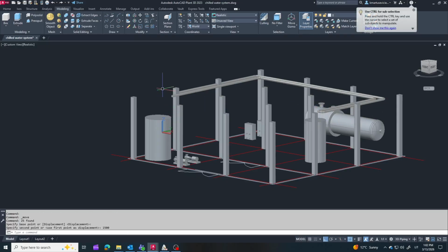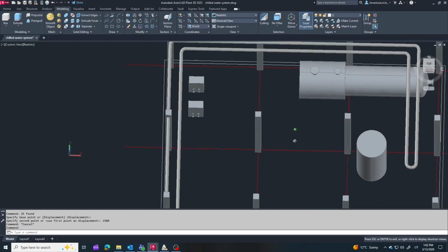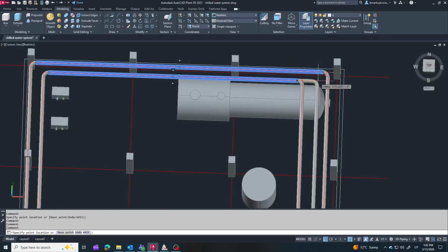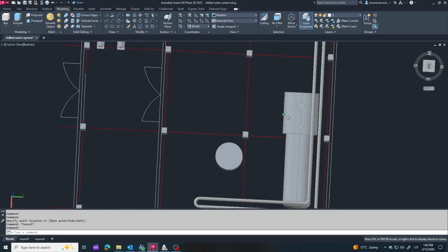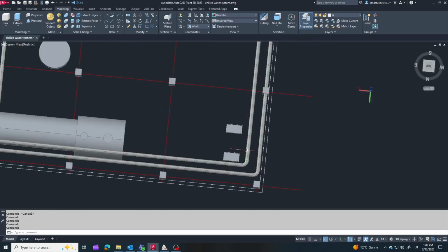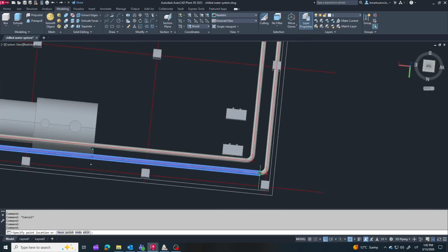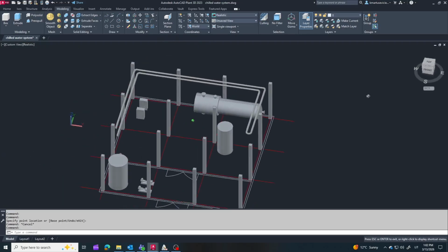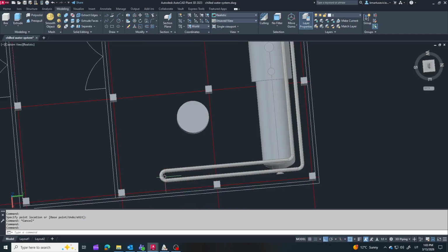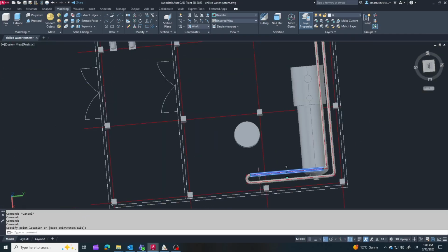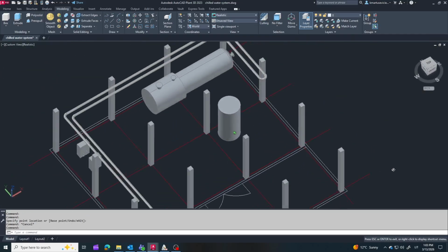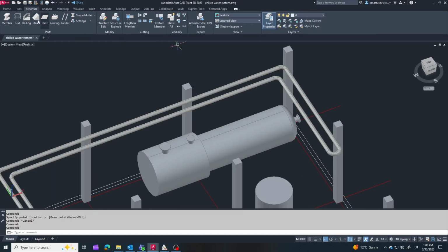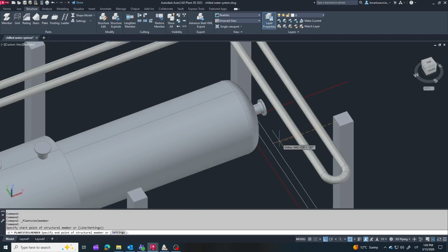The chilled water is distributed through a loop. One advantage of this layout is flexibility. Equipment can be connected at different points along the loop, so new users can be added later without redesigning the whole system. When designing the piping, it is also important to consider possible future expansion. If additional cooling equipment may be installed later, the pipe diameters should be selected with some reserve capacity. This way the system can handle larger water flow rates in the future without needing to replace the main pipelines.